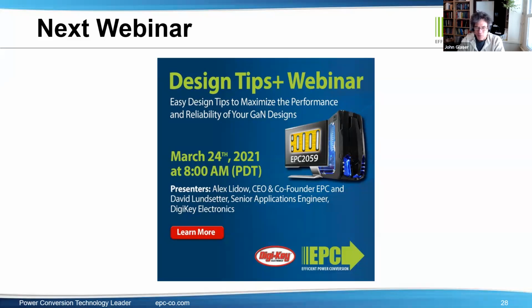And they work because in the high power systems, the laser duty cycle is limited because of the laser, and it's typically 0.1%, maybe 1%. And so the resistors can handle that for those very short pulses. In addition, we actually do some frequency compensation on the resistors because the resistors have a shunt inductance, and we think it's pretty accurate.